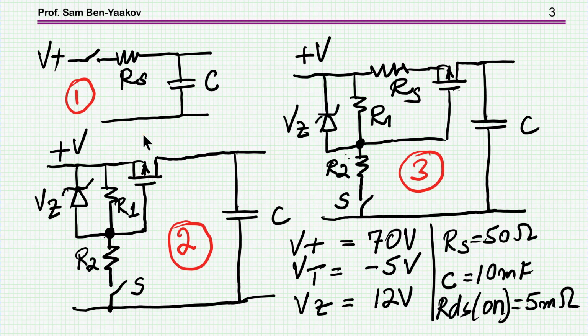There are many pre-charge circuits available that people have been using, and I am now showing 4 types. One is very simple, in which the current is limited by a resistor, R sub S. Here is the switch, we turn it on, and then the current flows here until this capacitor is charged. Of course, we're going to have here a switch for the main power later on. Power is not going this way, but will be coming through another connection. So this is the first circuit.